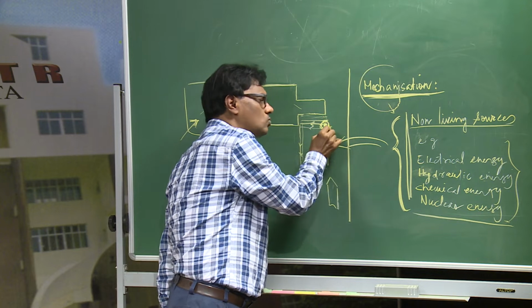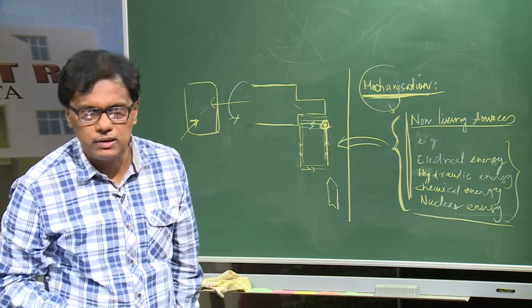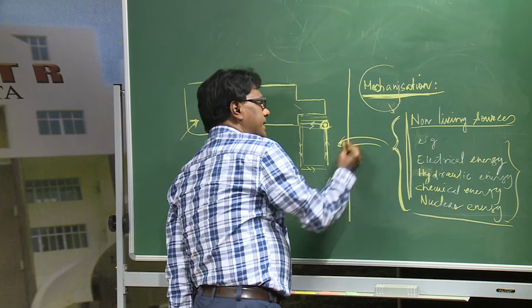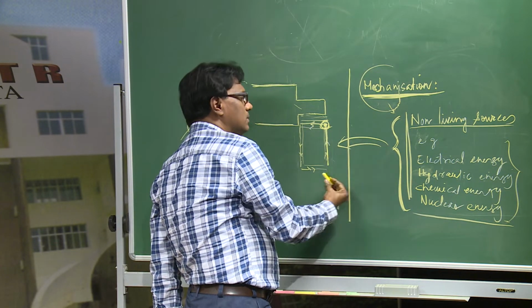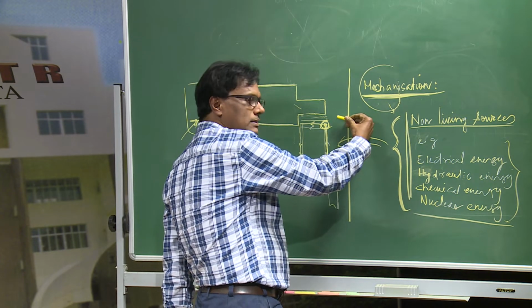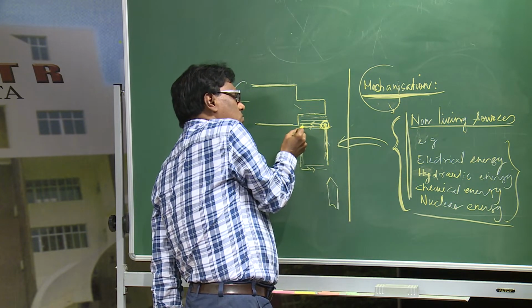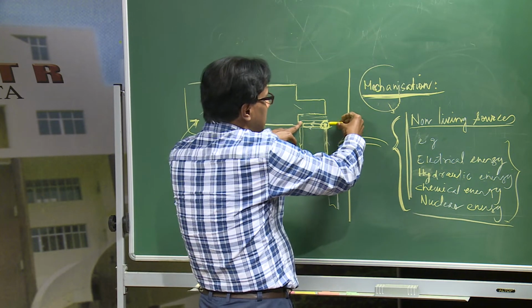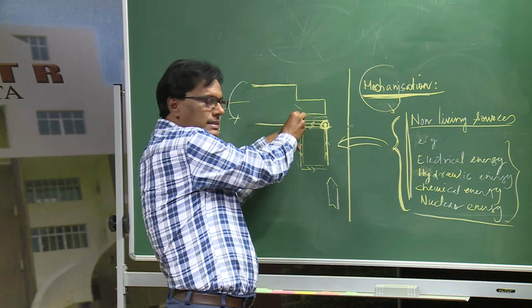It has to stop moving in this direction. Then the motor in another direction starts, and when it is stopped, the tool moves in this direction. When this position is reached, again the motor is stopped, so movement along this direction is ceased.